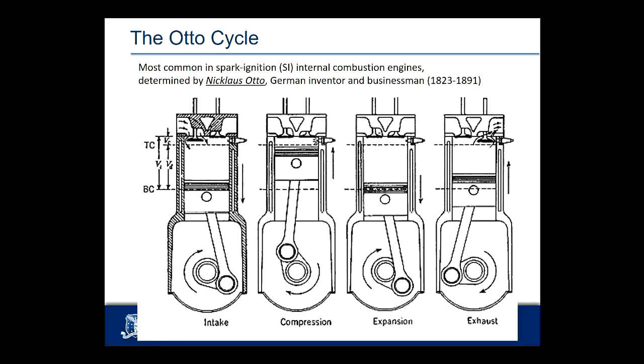That flame goes bang. Hopefully it doesn't explode, but it burns through the combustion chamber. And then now that I've got hot, high-pressure gas, I let it push the cylinder back down again. That's the expansion stroke. So intake, compression, expansion, exhaust. On my way back up, I use the momentum of the engine as it's pushing around to push the air back out again and then get ready for the next cycle.